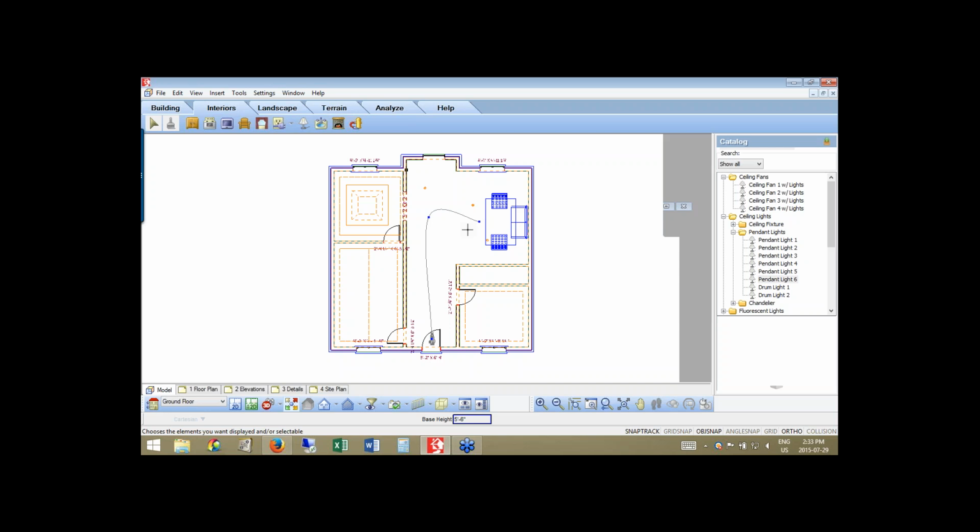I needed to turn that corner, so I need a control point there to say I'm now going in a different direction. You'll also need one if you want to change the height. As I go up the stairs, I need a control point. Maybe every stair would be a little bit jerky in your animation, but maybe up a couple of stairs and then up to the very top, you can change the height at these control points as well.